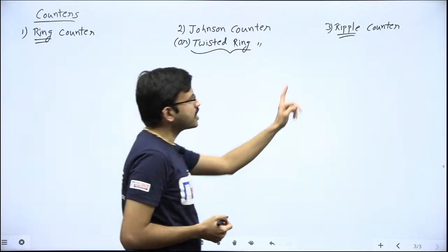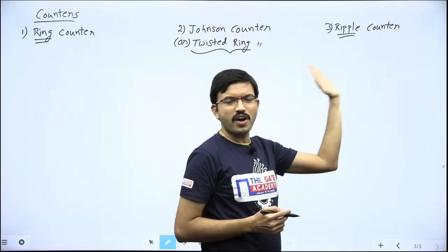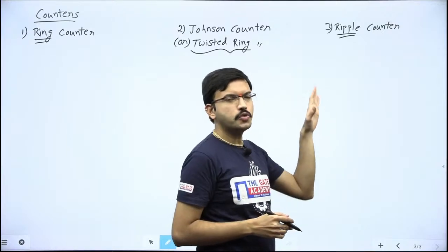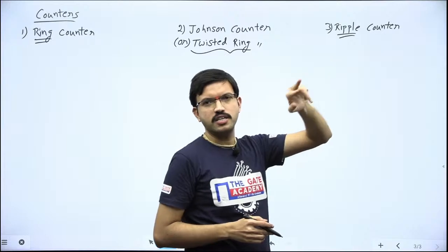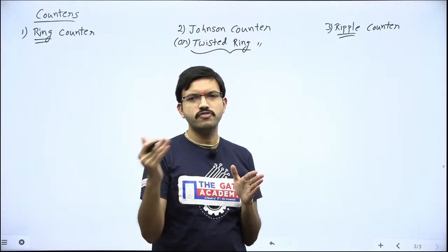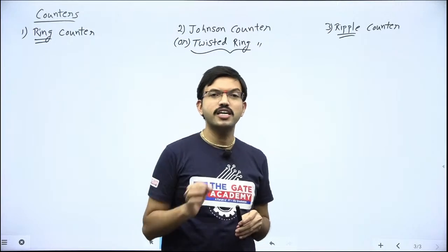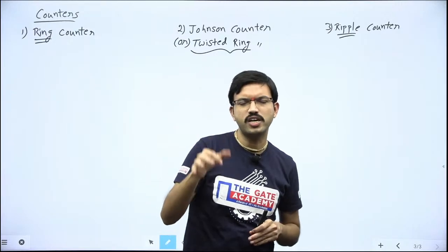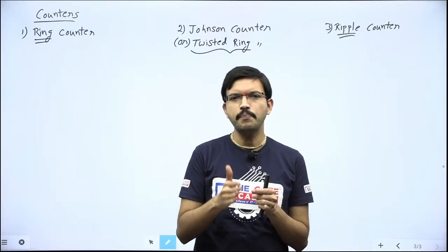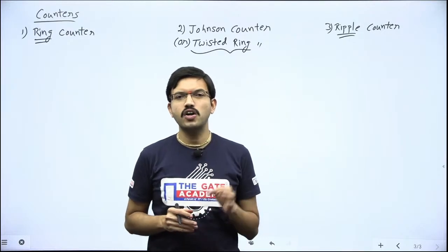In the ripple counter we use T flip-flops. Here all the flip-flops do not have the same common clock signal. The output of one stage we give as the clock signal for the next stage. That particular phenomenon is called ripple phenomenon. If you recollect, in the binary adder, the output of one stage we give as the carry input for the next stage, right? That is called ripple phenomenon. When you drop a stone in water, what will happen? The waves will be displayed, right? One molecule will bombard with another, and another molecule with another molecule, like that displacement will happen, right? That particular phenomenon is called ripple phenomenon.